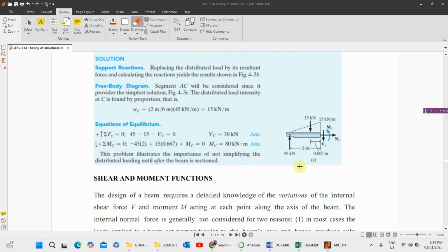So now let us consider this particular member. I want to take moment to this particular point here. So how do we go about that? We start from this particular member here. Now this member, if you want to take its moment to this particular point, it's going to travel in this form. It's moving like this to this point. Now is this direction clockwise or anti-clockwise? This is clockwise, and anti-clockwise is positive, so what we have here is clockwise, which means it will be negative.